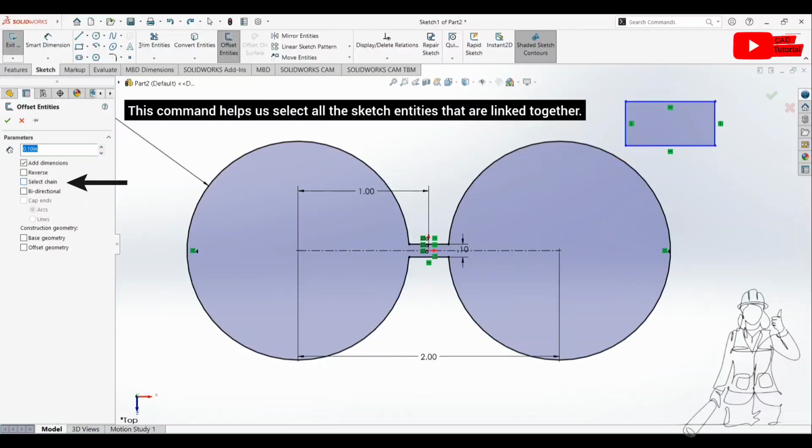We should uncheck this option if we only want to offset a part of the shape. For example, to offset only one line of a rectangle, uncheck this option and select one line, and you see it just offsets one line and not the whole rectangle.